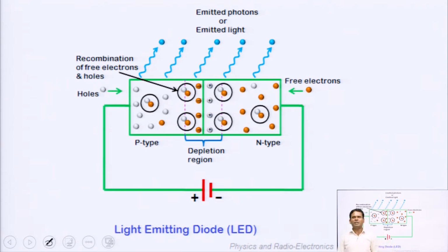On the other hand, in the p-type semiconductor, holes are in the valence band, that is at a lower energy level. When electrons cross the junction, this means when electrons shift from the conduction band of the n type to the p type, then the electron will fall into the valence band. This is called the recombination of electron hole pair.